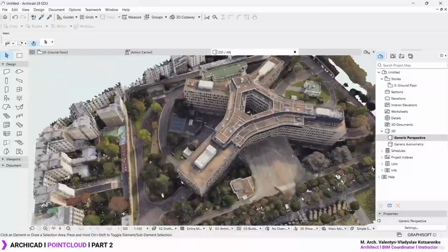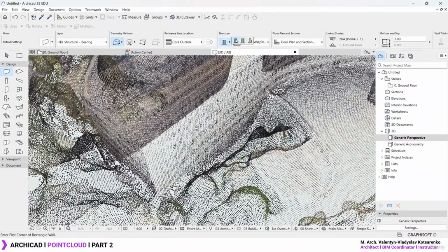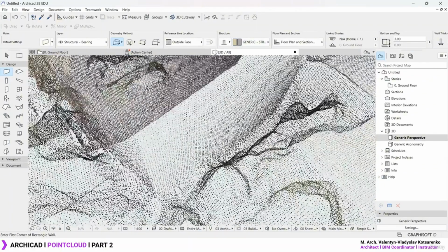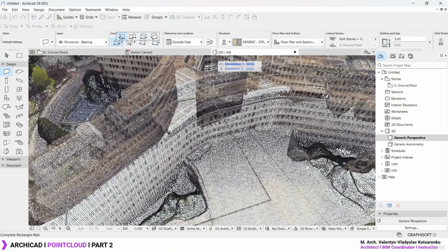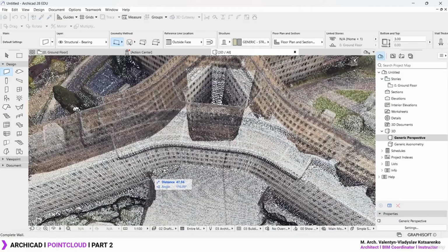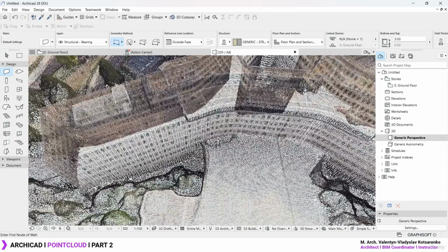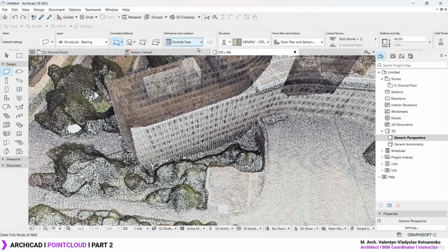The interesting thing here is that now, for example, you can take the wall tool, you can set basic measurement here, and then snapping the object, you can directly and freely start to model following the different snaps you get over here. So if we set this to maybe 40 meters, let's see if it works out.